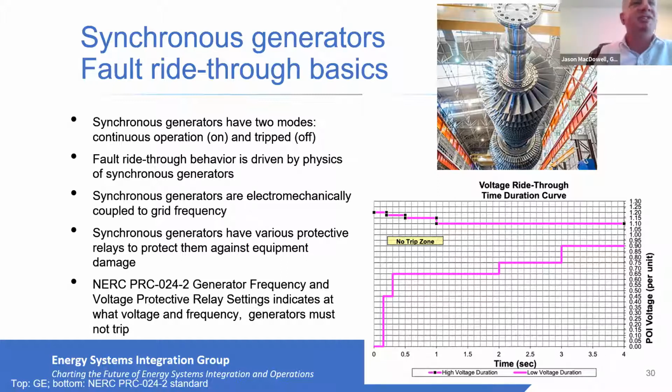Let's say you have a storm that comes through, and that storm causes two phases of a transmission line to touch one another, or causes a transmission line to break and fall to ground. That causes an electrical fault. Those faults are normally detected very quickly and cleared very quickly. But during that event, we want to make sure that when those electrical faults happen, no other generation outside of where you have that local disturbance is tripped offline. We want to make sure that all other generation remains online, undisturbed, and supports the grid.